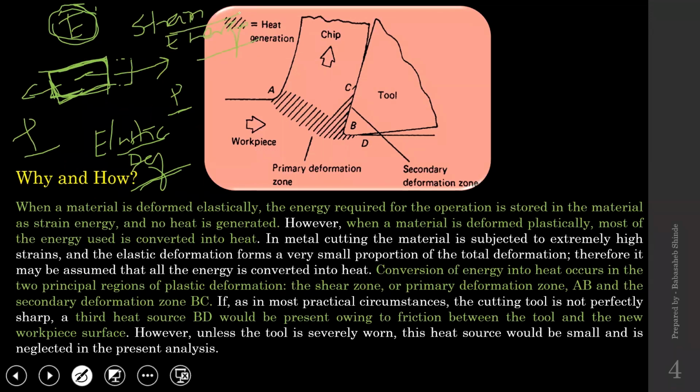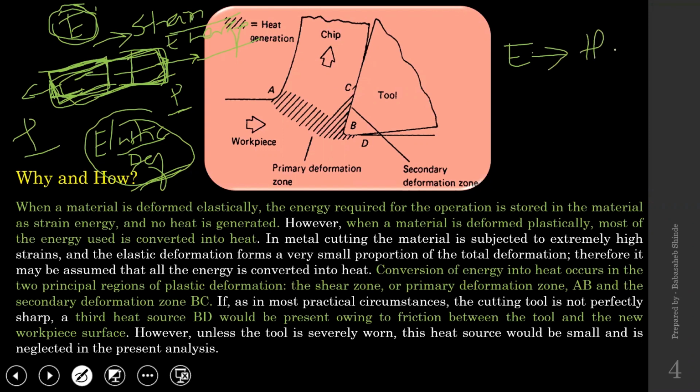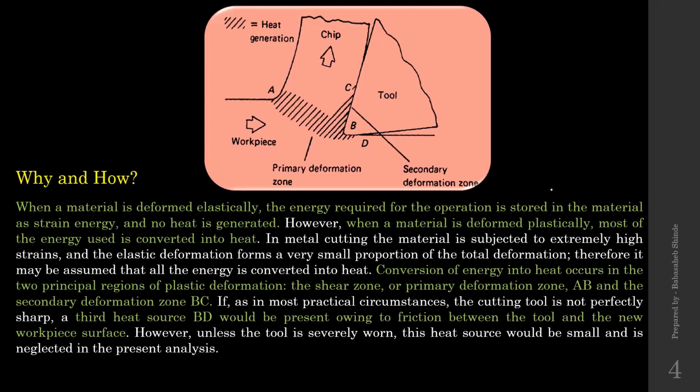Okay. So if elastic deformation is there, energy is converted into strain energy. Reverse to that, if I stretch it beyond this point and after that it deforms plastically, now this is a permanent deformation. In case of plastic deformation, whatever energy I have provided, all the energy gets converted into heat. Okay, let's continue.